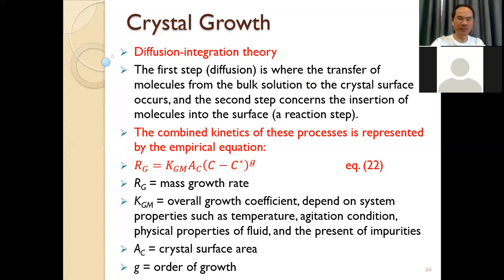As I talked to you, the growth rate depends on the diffusion of solute to the surface of the crystal, and also the integration of the solute on the surface into the site. There are many theories that describe the growth rate. The common theory is the diffusion-integration theory, meaning these two steps. The first step, the solute diffuses from the solution to the crystal surface. The second step, the solute on the crystal surface is inserted or integrated into the site. Sometimes we call it the reaction step.